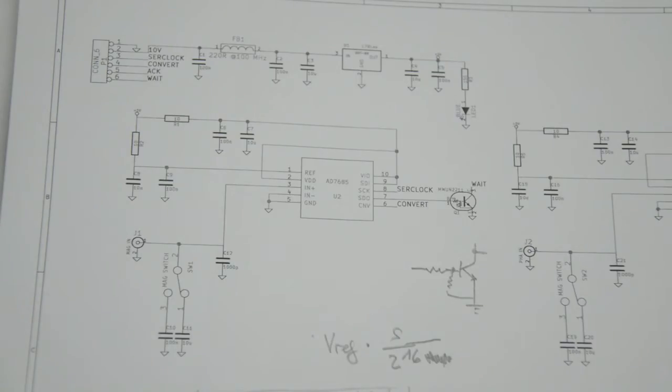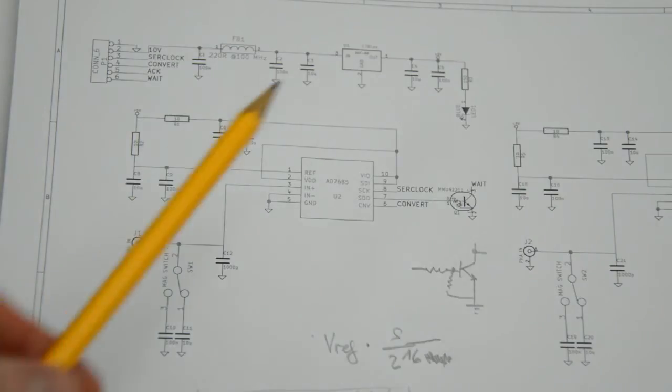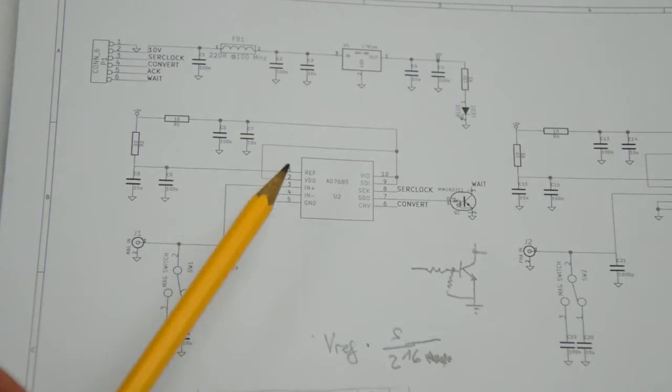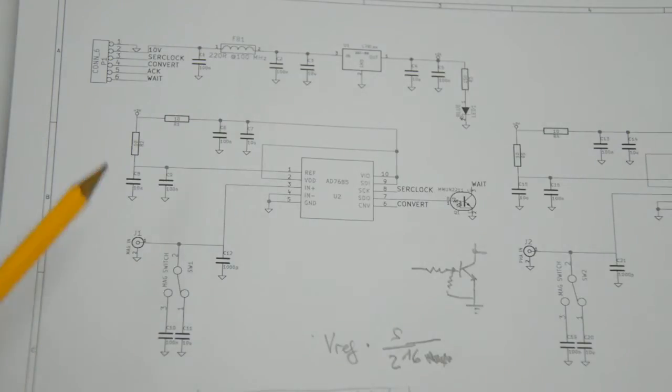So once you have this all running, maybe once the system has warmed up, you get a fairly standard output voltage here. And if you use this as a reference, it means that the measurements that you take might be off by some amount, but they will be off consistently. Although if you really want better accuracy, of course you use a precision reference and also do all sorts of other tricks to improve on that.